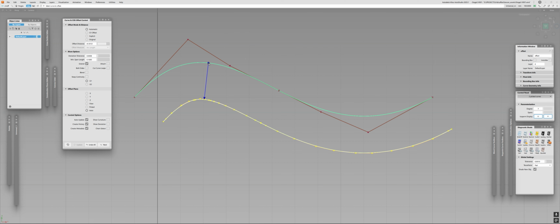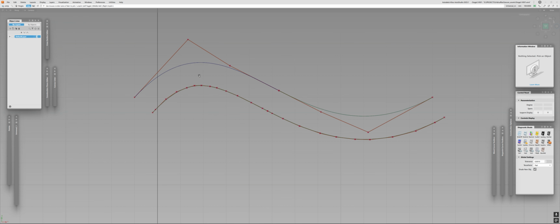So what I'm going to do is I will just click on the curves. Let me change the direction inwards. I will talk about why we need to do it inwards, not outwards, all the time. But for now, let's say that I have an offset here. And if you look at the curve, you immediately notice that the newly created curve is quite different from the original one. First of all, we have quite a few spans here, literally a lot of spans. And actually, if I select one of the curves, you're going to see it has 11 spans.